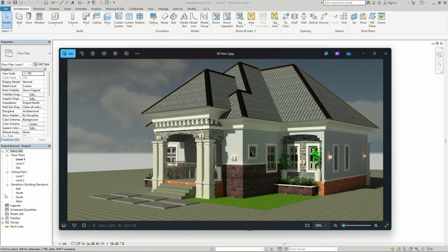Then again, this level comes in item, and Revit has a series of calculated heights. So if I'm taking a level from the ground at 800 millimeters, then I should take the next level to the height of the house to this point, 3000 millimeters.